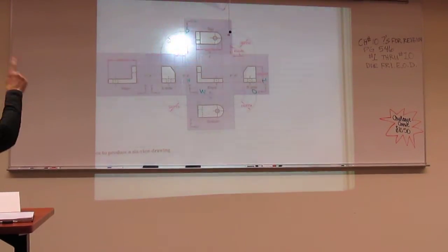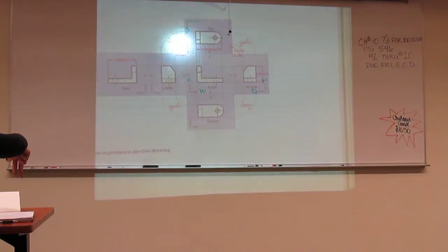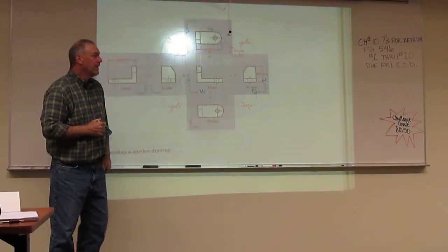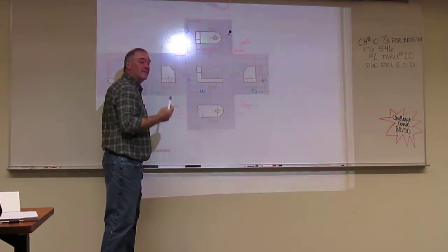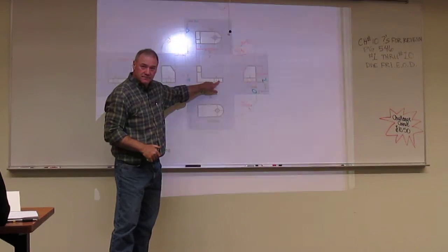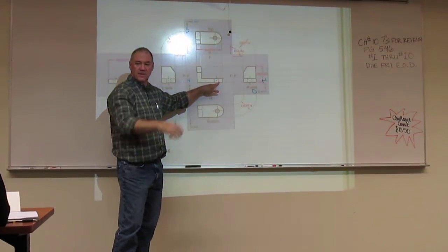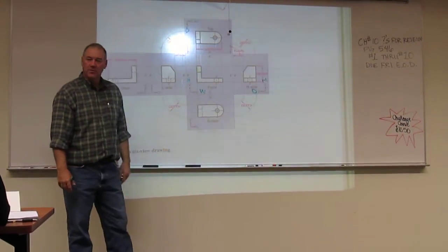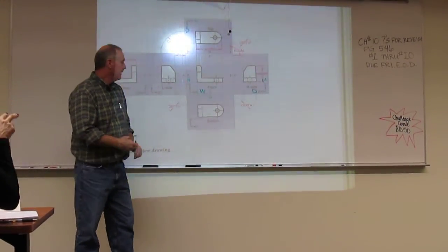Yes? So my question, on this drawing here, if that hole didn't go all the way through to the bottom, would you describe that on the front view and not make the line go through? I mean, how would you know that it was just bored partway? Or would you have to show the bottom view? This describes the geometry of it. It goes through. One, we've got these hidden lines that are limiting elements. They aren't an edge, right? Those are limiting element lines, these right here. Okay, because that's where the cylinder would leave our line of sight. They go from top to bottom. This has to be a through hole. If there wasn't, you would only have one dash in there?